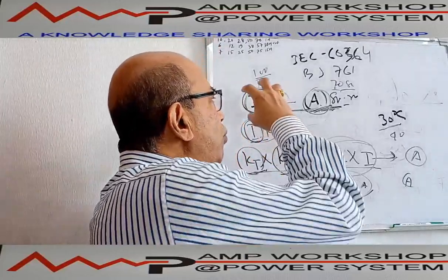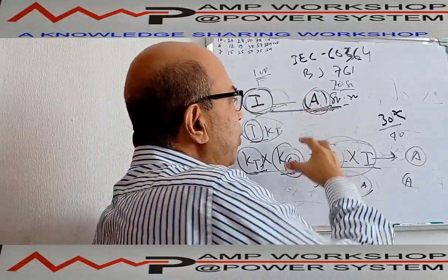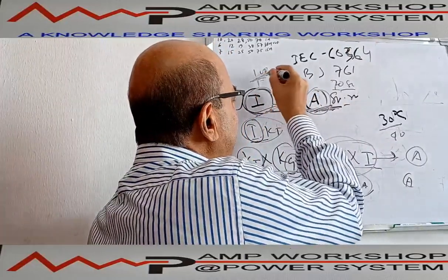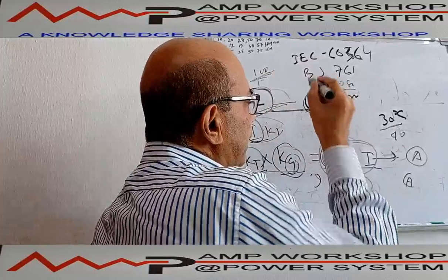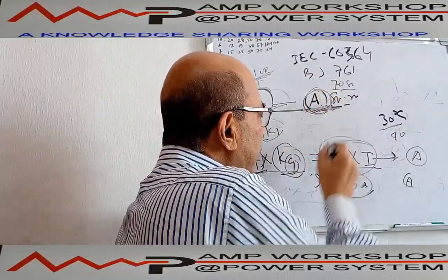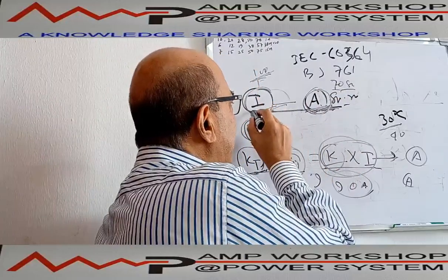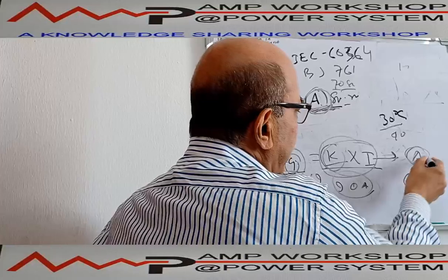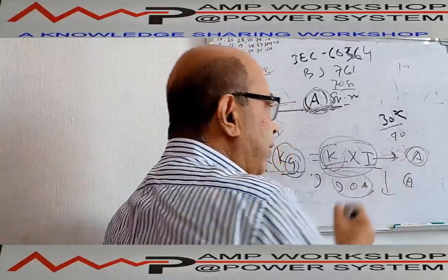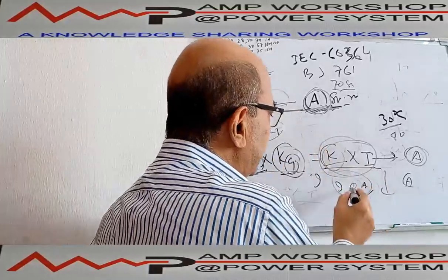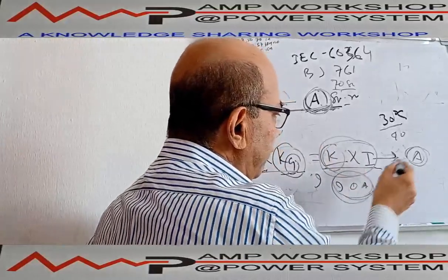That means now if we have a 100 ampere current, then we have to increase the cross section area. Suppose my full load current is 100 ampere, based on that I see the cable is A square millimeter. Now the same A square millimeter cable, when I apply the derating factor, is carrying 90 ampere, but my current is 100 ampere, so I cannot use it. Then I have to go back to the table.